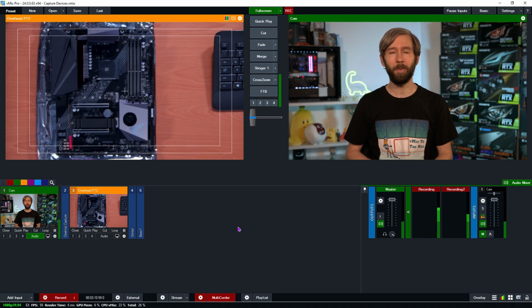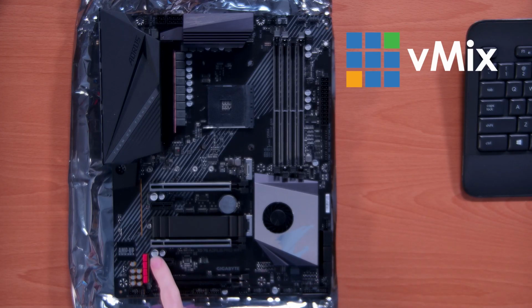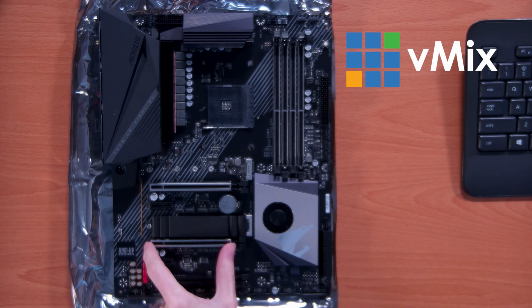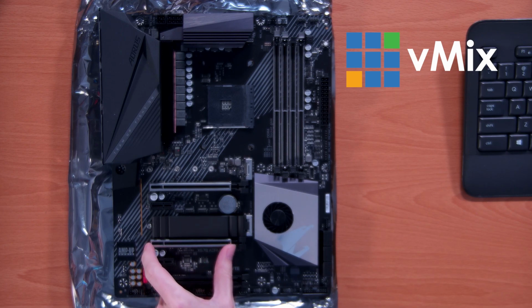One final thing that might be a little bit tricky is that you might get 2 measurements when looking for PCI Express slots and lanes with your motherboard. For example, this slot here is physically a by 16 slot, so it's the width for a by 16 card. However, only 8 lanes might be connected to it. So mechanically it's by 16 because that's the width of it, but electrically it's only by 8 because you only have 8 PCI Express lanes available to that particular slot. That's something to be mindful of when purchasing as well.